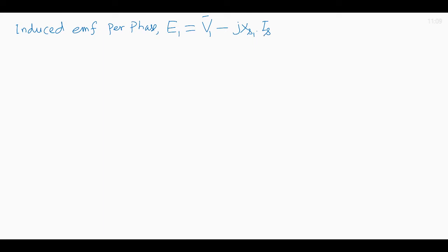The current is the rated current, as mentioned in the first bit, and V1 because of constant V by F control is 4763 volts, minus reactance XS1, 6.75 at 90 degree, and current IS 349.9, the rated current, but with power factor 0.8 leading, so angle cos inverse of 0.8.